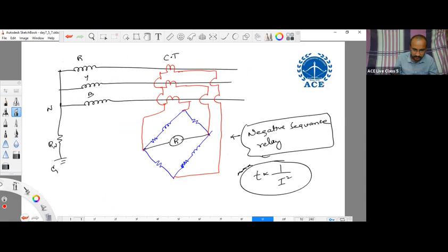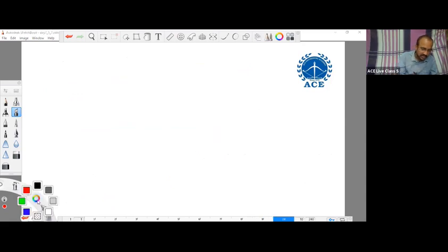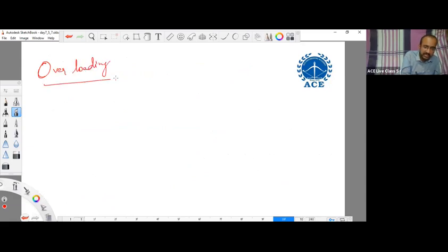Okay. Now let us go for the next abnormal condition, that is overloading. Overloading means what? This is not a fault condition, sir. This is an abnormal condition. A fault is different; a fault will result in overcurrent. Here there is no fault, but the quantity is exceeding its value.